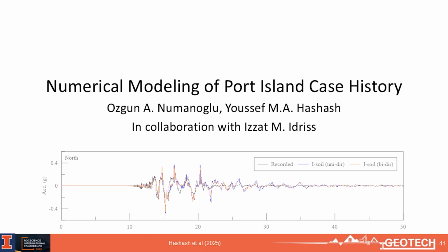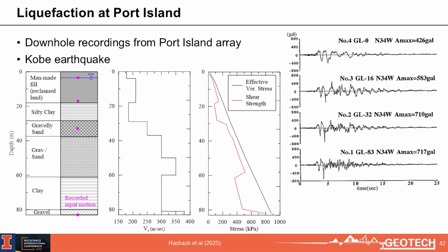And there, even though they did not measure pore pressures, there was clear evidence of liquefaction, because if you look at the records on the left, as you go from the bottom to top, do you see there's a reduction in the number of these wiggles? It's filtering high frequency. Soil filters it, but then also you see a little bit of long period attenuation and amplification, and that's actually a result of liquefaction.